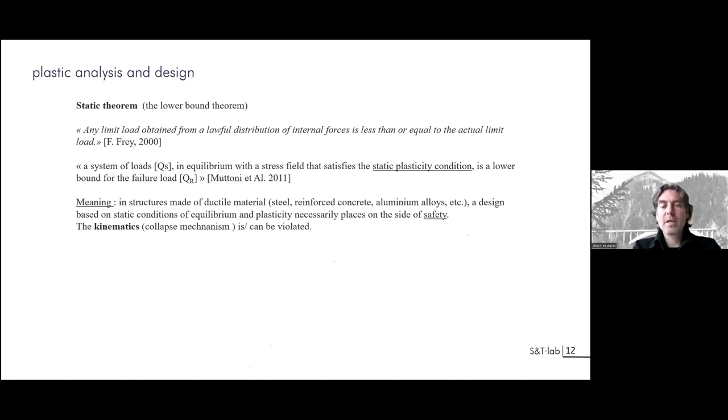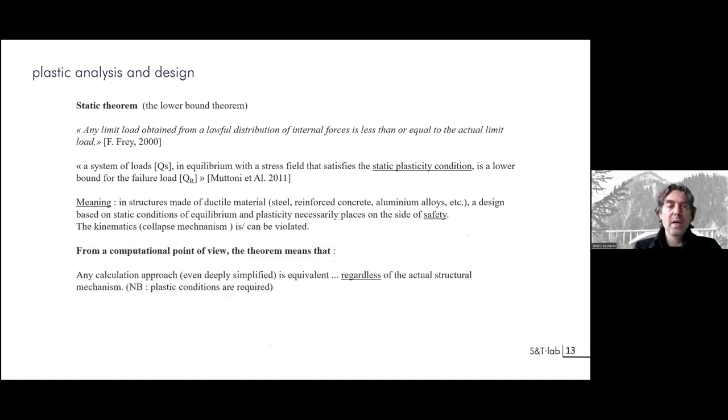Of course, the kinematic or collapse mechanism won't be correct for this approach, but you have a lower bound result. It means also that whatever approach you use to design or dimension your structure, if your structure is dimensioned according to this principle, you will get a safe result.